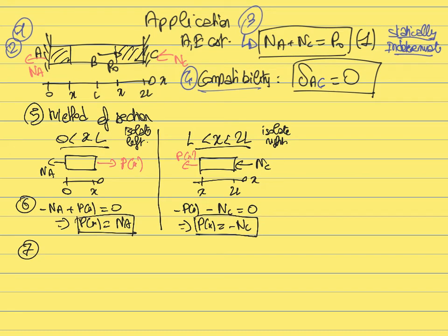So here again, we will use the elongation formula. The general elongation formula is that the elongation between A and B is the integral between A and B of the load divided by the cross section divided by the Young's modulus. When we apply this formula, we always need to be very careful of those three quantities: load, cross section, Young's modulus. Do they depend on x or not? If they depend explicitly on x, then we need to solve this integral.